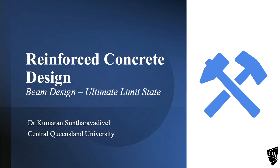But if you don't know the depth of the beam, then you should start with a deflection check, so that your assumed depth can be verified whether it complies with the deflection requirements. That's why we started with the serviceability limit state.